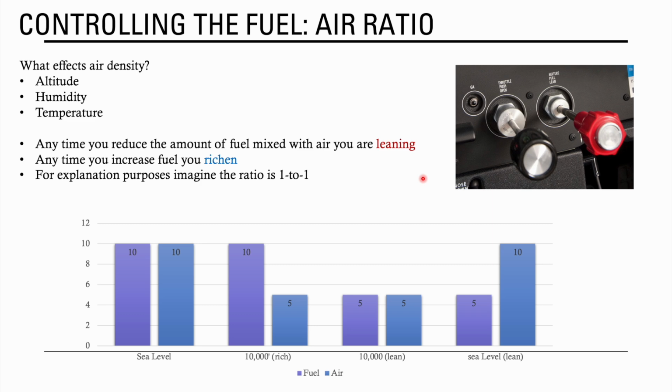Old school method is just lean it until the RPMs peak, and then once they start to drop off, or if the engine starts to get rough, you just put it back in a little bit. That's the rule of thumb method.